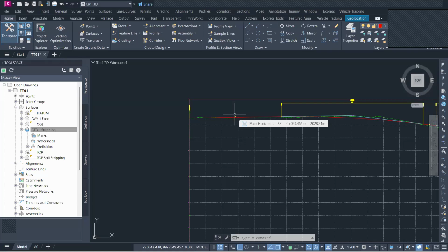You design the formation level first, and the formation level is reached when you've done your final earthworks, or when you've prepared your subgrade and it is ready. It is your final subgrade, and you're ready to do the pavement layers. So you're ready to drop in the sub-base, you're ready to do the base, and all of this. Now, there are two specific scenarios.